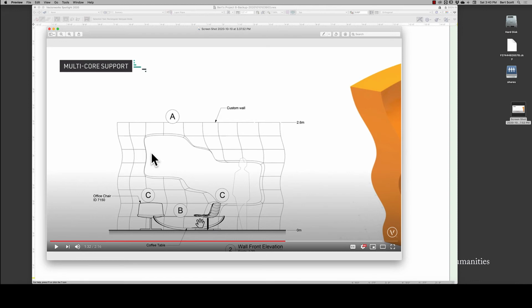And if you study this, what you'll notice is it seems to be broken into the original 8x8 grid that we started off the subdivision with. So I tried applying a grid texture to it, and that didn't work because of the way that Vectorworks applies textures. I tried just doing the line render mode.